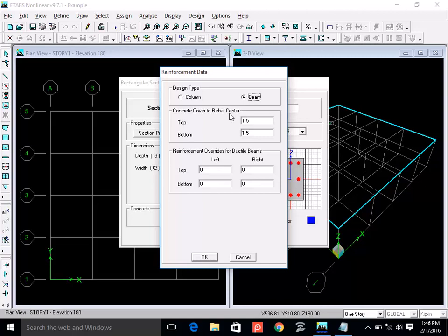No matter what units designers are using for their real design, the bar sizes are used in FPS units. Sometimes you will see that drawings are prepared in SI units, millimeters and meters, but the bar sizes are still the FPS bar sizes. So you need to be familiar with these sizes. I will show you a table. You may have it in your concrete book by Dr. Zaid Siddiqui, a table at the end which shows all the bar sizes.